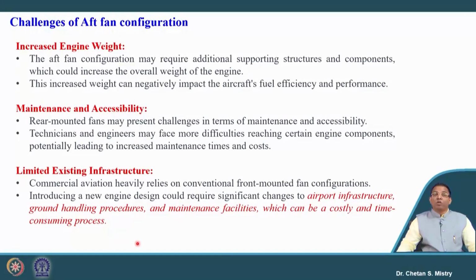So, do not get confused with what we have previously discussed. Previously, in terms of advantages, we talked about reduction of the weight of the engine. Here we are discussing the overall weight because of the engine. At the same time, since we have kept our fan on the rear side, maintenance and accessibility is a little bit of an issue, and that will lead to increased maintenance cost as well as time.